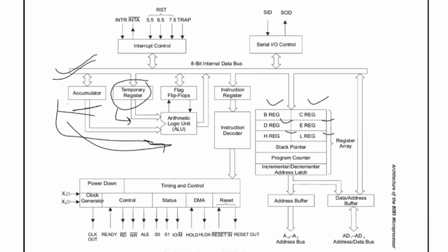You can see here the output of this ALU is connected to the internal data bus. That means the result of the ALU operation is always transferred to the accumulator through the internal data bus.